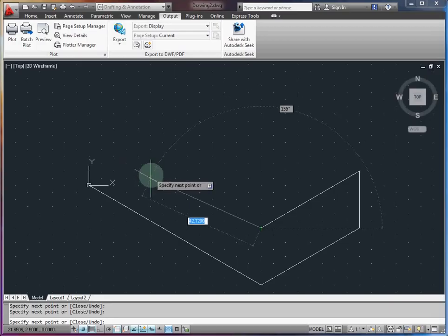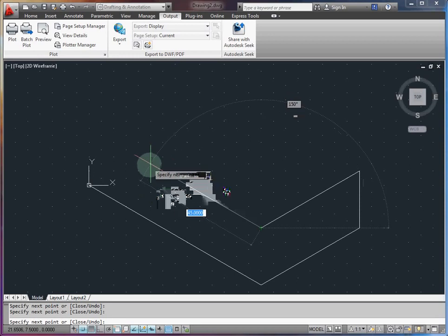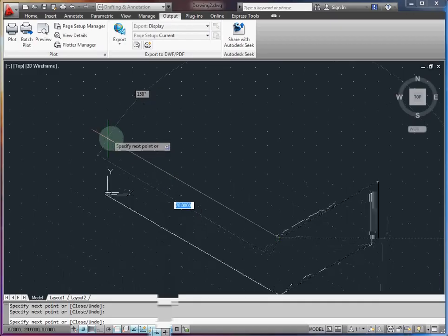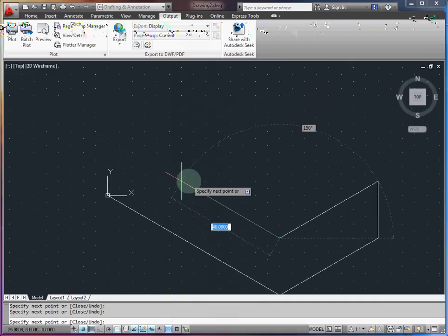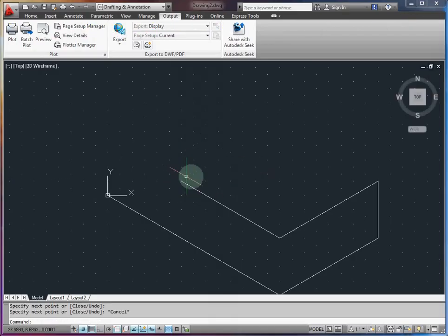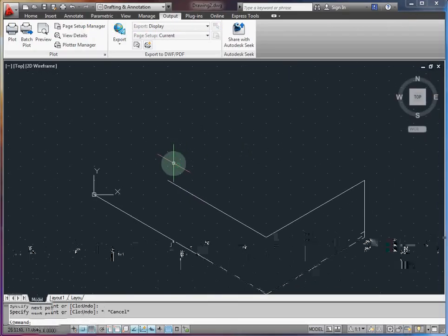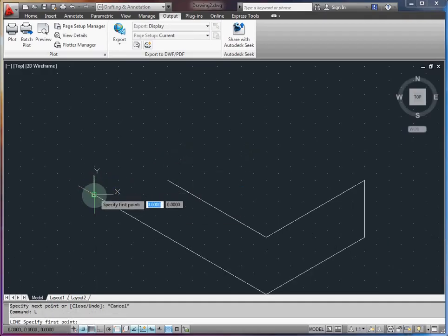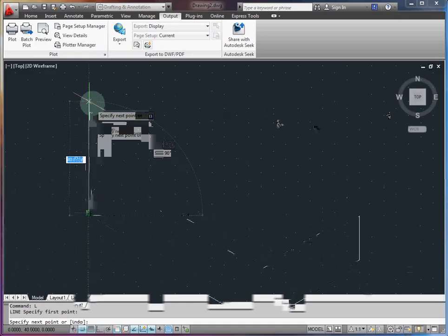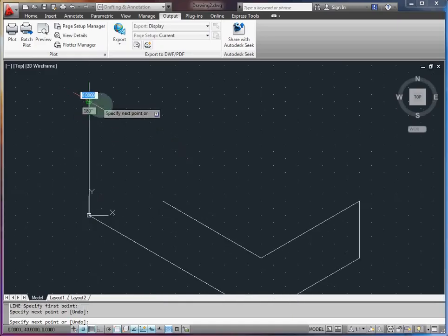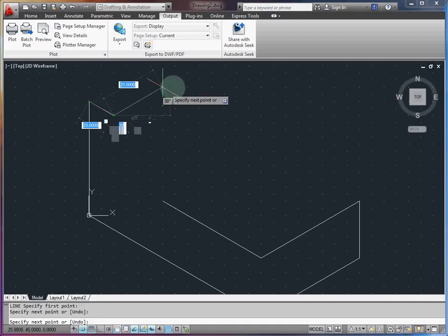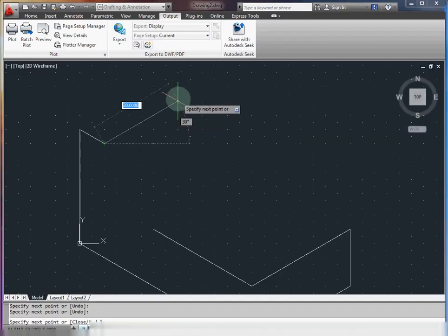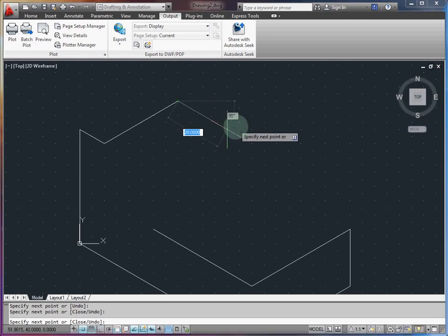Looking at the drawing, you'll see that there's an angled feature that ends about here, and that is at the 30 unit mark, which is 5, 10, 15, 20, 25, 30. So I can stop that line here just before the angled feature. I'm going to continue drawing the back side here. I'm going to come up, this is a total of 40 units tall. It projects forward 10. And then at this point, I'm just going to fill in the top of the part. So that's 30 units over, and this feature, remember, projects a total of 30 units out. So I can trace the outline like so.